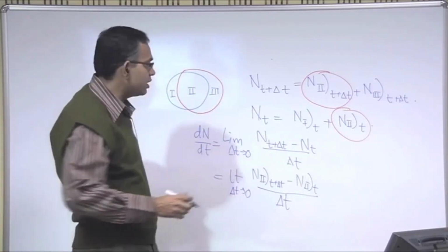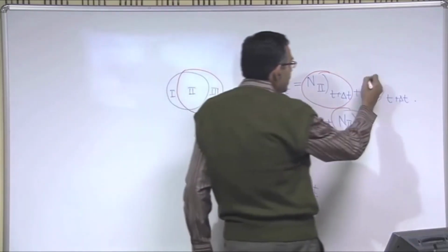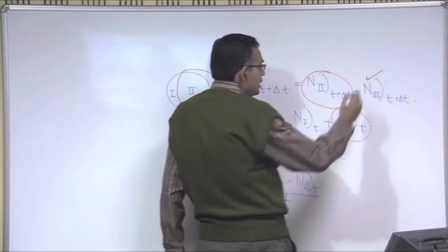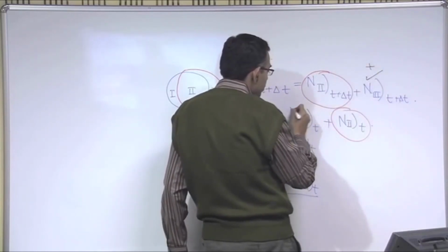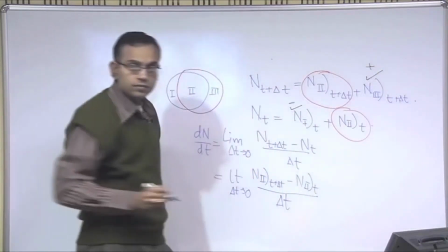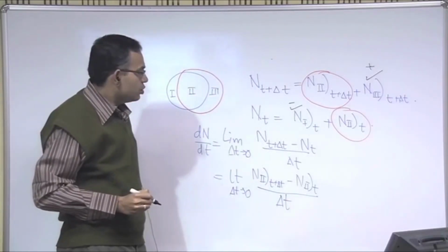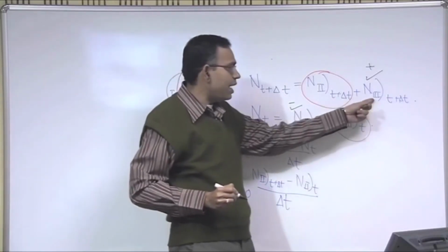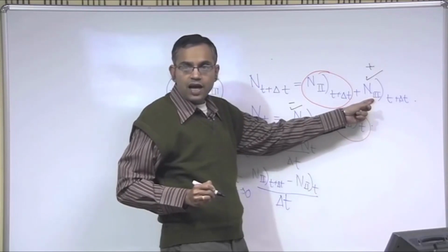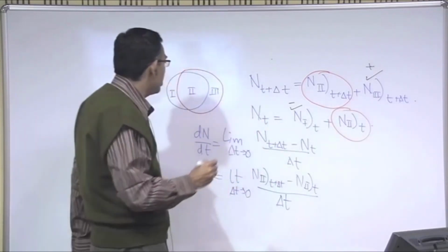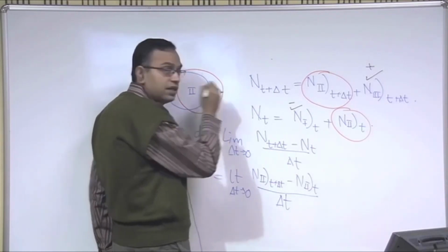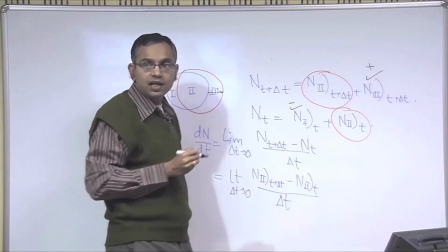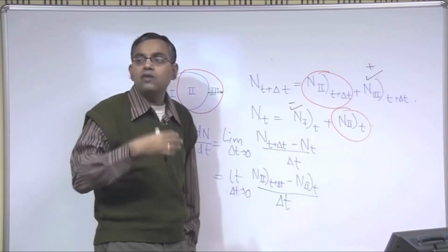What are the adjusting terms? This is a term which is a positive plus term and this is a term which is a minus term. Now if you divide this by delta t and take the limit as delta t tends to 0, that is the property that is transported across 3. So, that is nothing but the rate of outflow of the property.